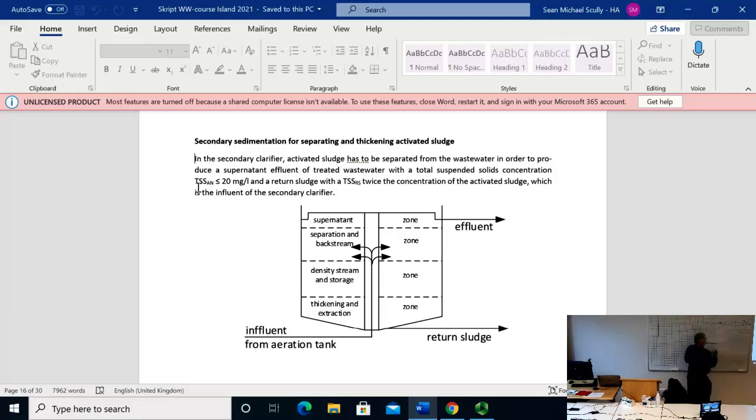And then those 2 liters go in here. They have a solids concentration of maybe 4 or 5%, and then we reduce that to 2%, and then we dewater it and increase it to 25%. So at the end of the day, we have something like 0.3 liters per day. So in the effluent, you will find something equivalent to maybe 99.7 liters per person a day.